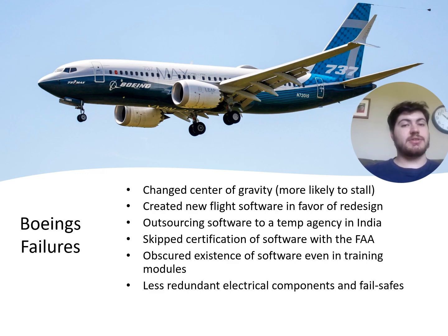In fact, until the first crash of a 737 MAX in late 2018, no one outside of Boeing even knew of its existence, of the MCAS, or the design of the systems feeding the data into the MCAS. Speaking of which, they also skimped on the standard number of detectors that were supposed to be used for determining the angle of attack. The standard number of detectors is 4. For the 737 MAX, it was reduced to 2, and the MCAS only ever reads from 1.